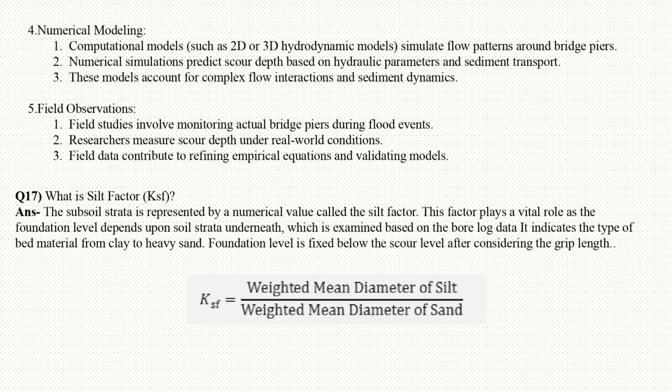Question 17. What is silt factor, Ksf? Answer. The subsoil strata is represented by a numerical value called the silt factor. This factor plays a vital role as the foundation level depends upon the soil strata underneath, which is examined based on the bore log data. It indicates the type of bed material from clay to heavy sand. Foundation level is fixed below the scour level after considering the grip length.